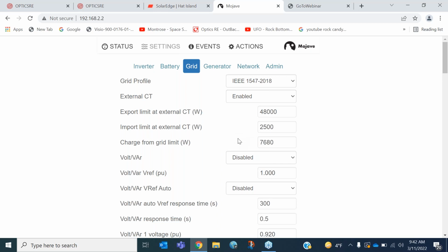And there's basically 4 settings. This is the one that says the import limit. There are 3 settings for the battery, and really just 2 depending on what battery style you have. One is that, hey, you can take this many amps out of my battery. If it goes more than that, we will violate this import limit. I'm using AGM batteries, so if I come down to low battery cut-in, that says I have taken my battery as low as I want. So if I get there, then let's go ahead and let the grid handle it. We're not connecting and disconnecting from the grid. It's there at all times, and we're just using microprocessors to say at what point.